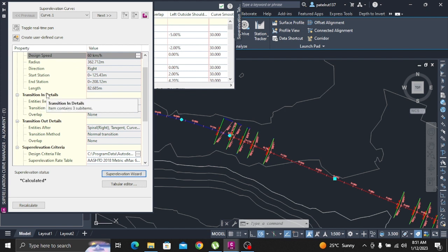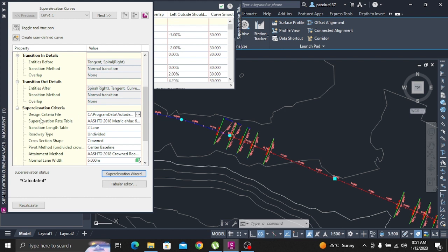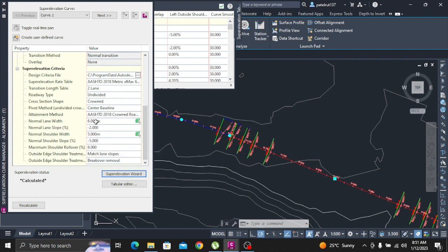In the top viewport, zoom into the middle of the superelevation view. In the superelevation view, select one of the lines. Right-click. Click Open Tabular Editor. In the Superelevation Tabular Editor, scroll down to Curve under Curve Point 3. Under Transition and Region, select the End Normal Shoulder row. The curve is highlighted in the bottom viewport, and the critical station is marked with a blue tick.